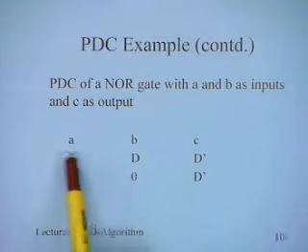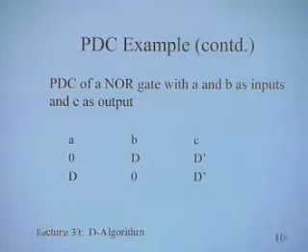You can see that the other input should be non-dominating input. For an OR or a NOR gate, the non-dominating input is 0. For an AND or a NAND gate, the non-dominating input is 1. We are not limited by 2-input gates, we could do the same thing for 3-input gates. I can do that for more than even 3 input gates, there is no problem.